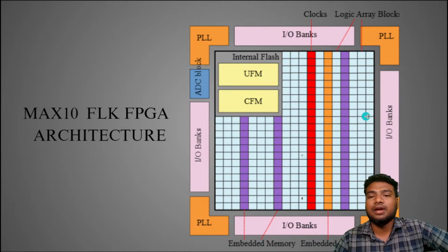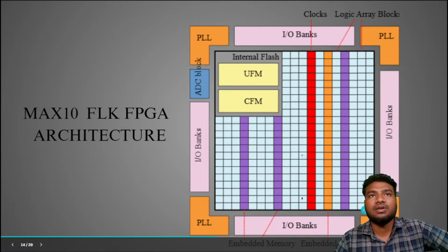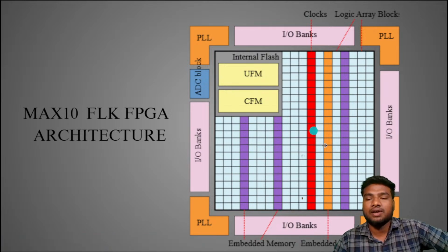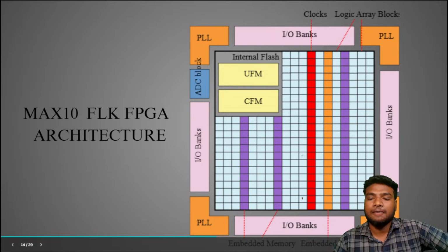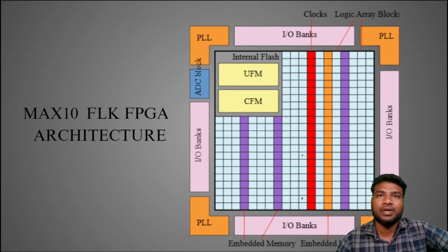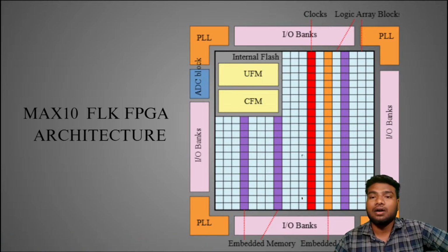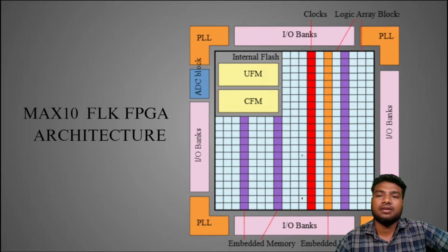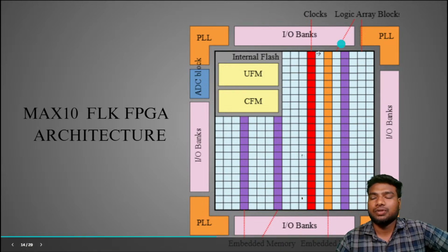And in some other condition we have to use 25 megahertz, so we have to reduce the 50 megahertz clock to 25 megahertz. For that we can use this PLL. So based on the frequency change we need, we can use the PLL. But all PLLs depend on the clock oscillator, our global clock oscillator. This is the main thing.